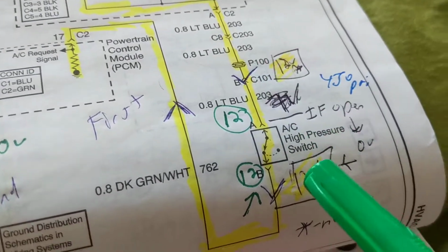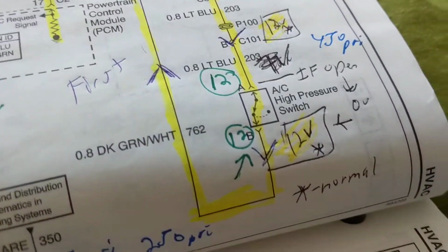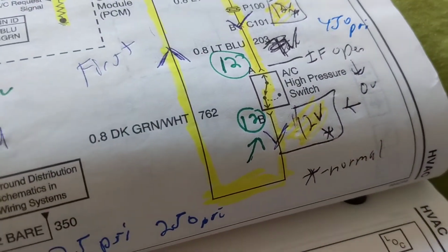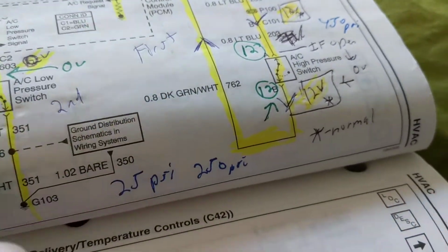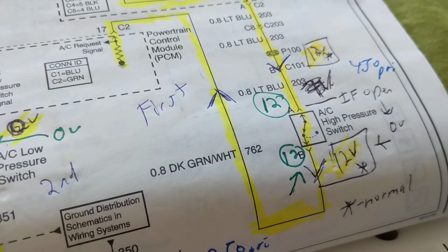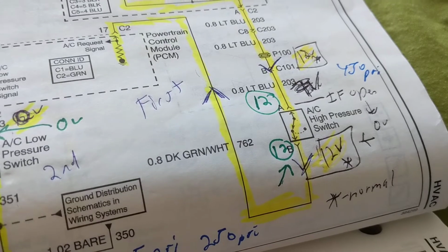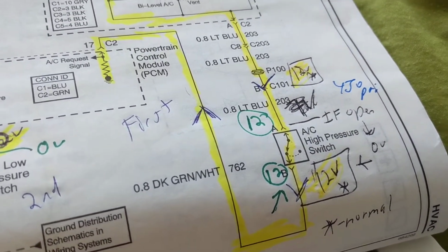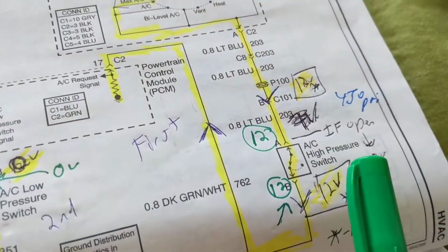But let's say that everything is okay, the high pressure side is okay. And again, before you start, you can always measure the static pressure without the compressor on, to see if it's balanced. You should get a balance on the low end and the high end, 75, 80, whatever. They should be balanced. So you have some pressure. Doesn't mean you have a refrigerant, but you have some pressure.